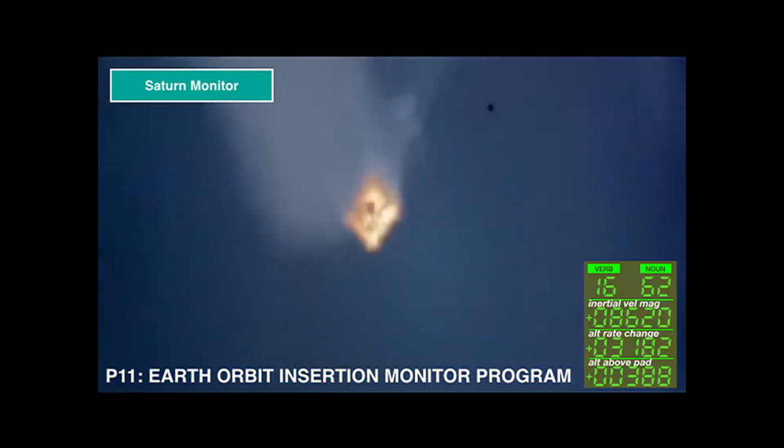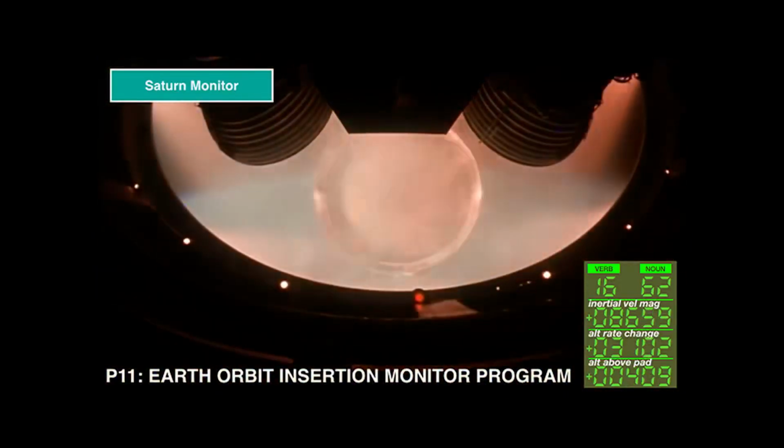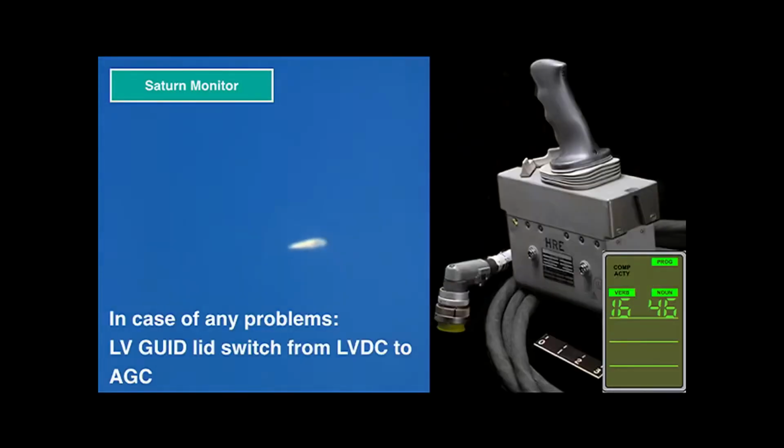The DSKY automatically shows verb 16, noun 62, which is velocity in feet per second, altitude change rate in feet per second, and altitude above pad in nautical miles. Note that the units and the position of the decimal point are implicit. And yes, the whole system was working in metric internally, but for the benefit of the American astronauts, the display procedures converted everything into imperial units. In case of problems with the Saturn computer, the Apollo guidance computer can take over full control of the launch vehicle. In extreme cases, astronauts could even steer the whole stack into orbit themselves with the hand controller.